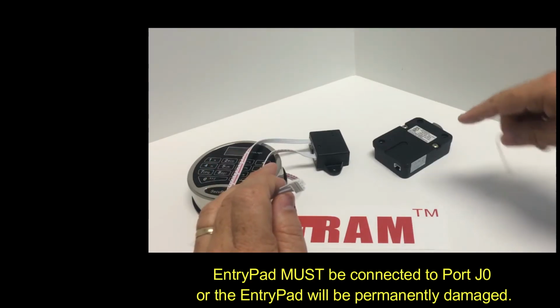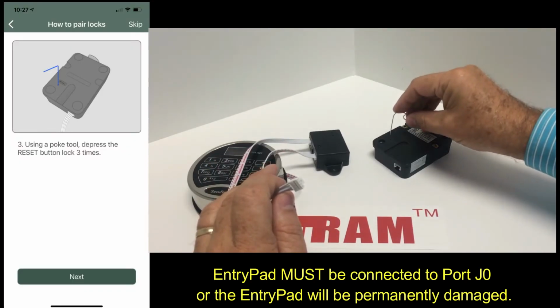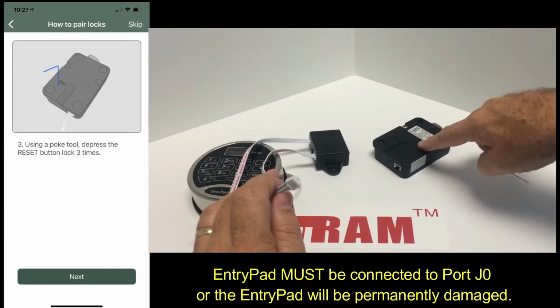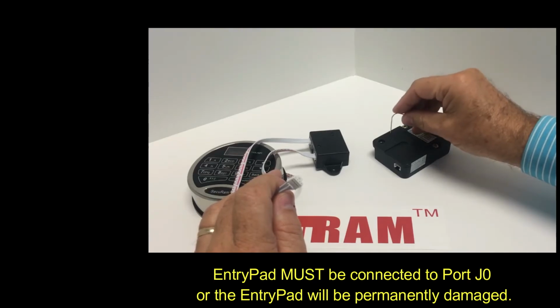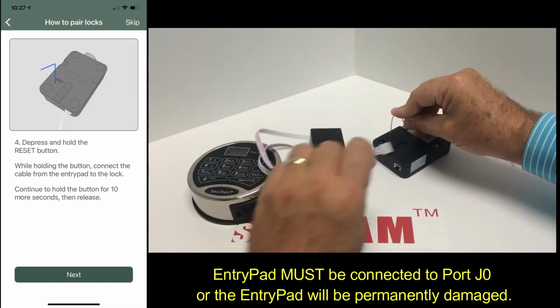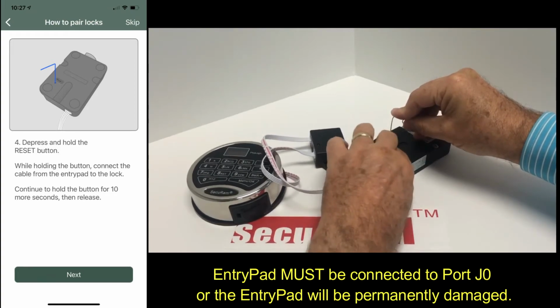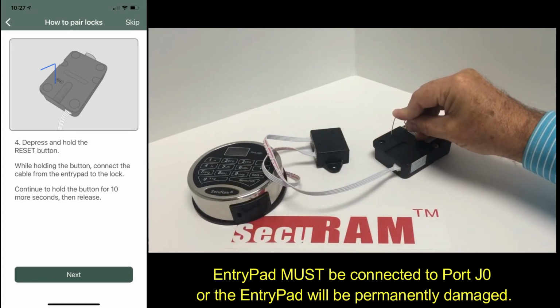In order to name this first lock, we're going to press the reset button down 3 times. That just eliminates any power that's in the capacitors inside the lock. Now we're going to press down and hold, and while we've held it down, we're going to connect the lock cable, which is connected to the junction box, to that lock and continue to hold for 5 seconds. 1, 2, 3, 4, 5.